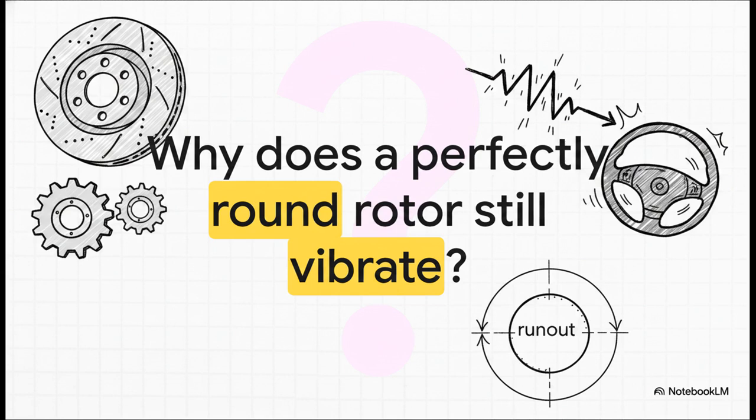Well, it's because a feature being purely round in its form doesn't actually guarantee it rotates cleanly around its functional center. If that deviation falls outside your rotational tolerances, the fabricated part is basically unusable. That vibration leads straight to premature wear on your brake pads, severe assembly degradation over time, and just a miserable experience for the driver. That destructive wobble right there, that is the exact problem we're solving today.